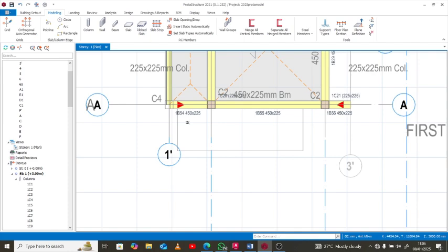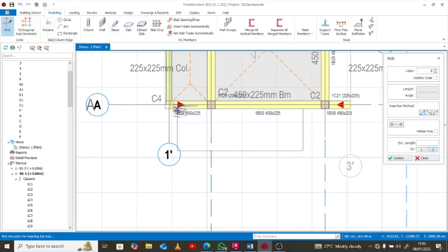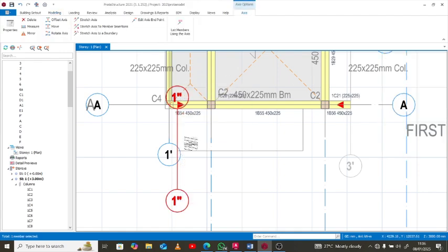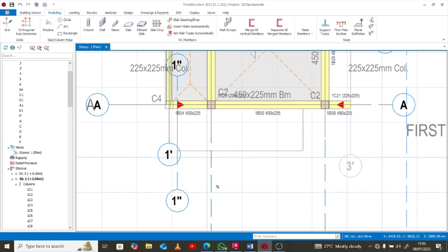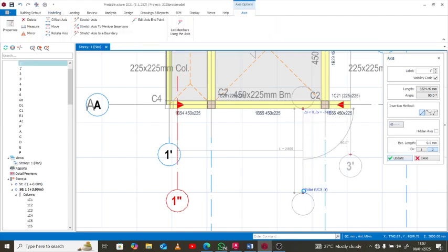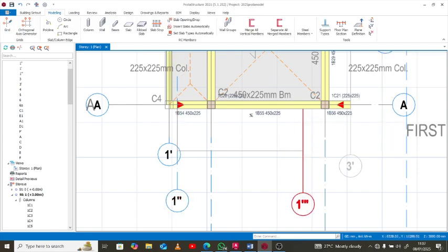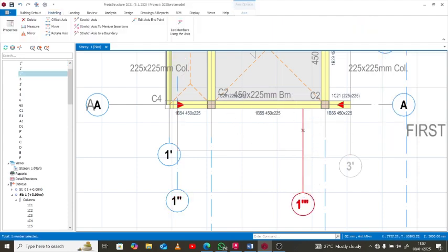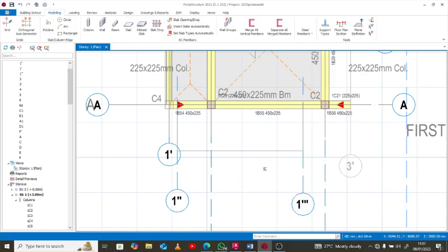So how do you form such a cantilever? You still need boundary lines. Let's call that, though it won't reflect in your design report. I mean, the grid line wouldn't reflect, but you need it to form that line. Let me take this off. Okay, and let us do the same thing here. So we can have our cantilever slab somewhere there.